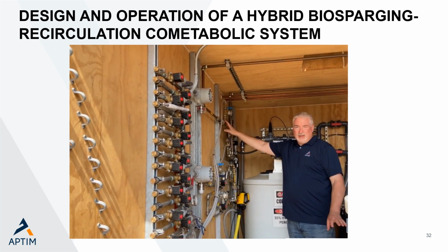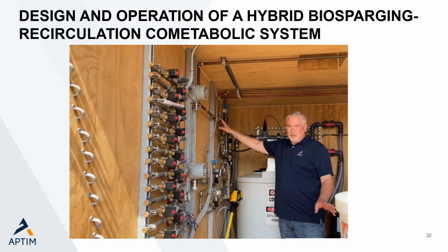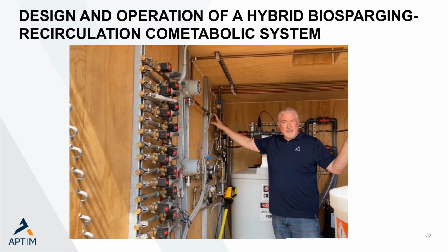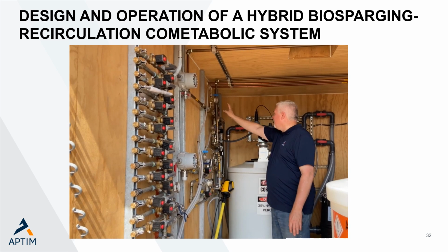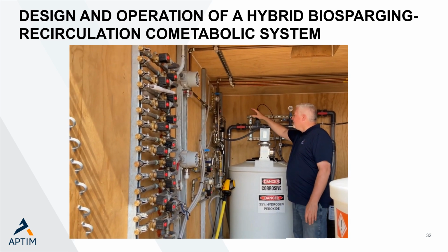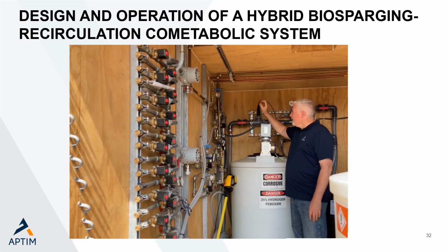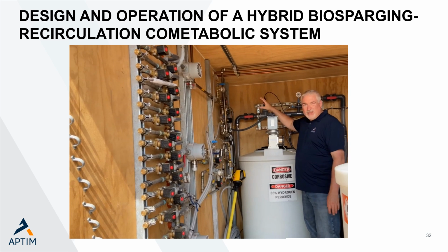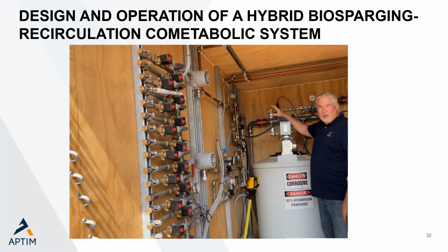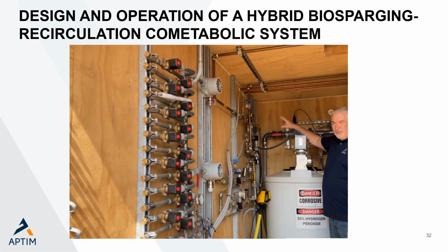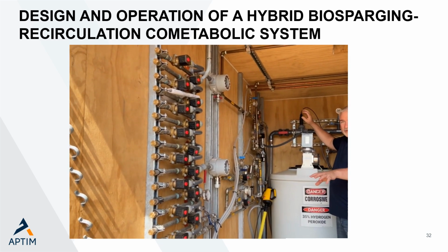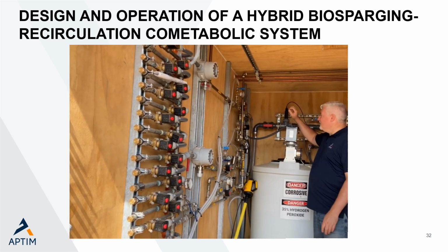Should there be any flames or explosions anywhere in the system, it will not let it get back to the oxygen cylinders. Another solenoid valve, and really the heart of this system is the mass flow controller. So this communicates with our PLC. We have put a set point as to what the flow should be at the well, and that controls the flow, and the solenoid valves control which well the oxygen goes through.